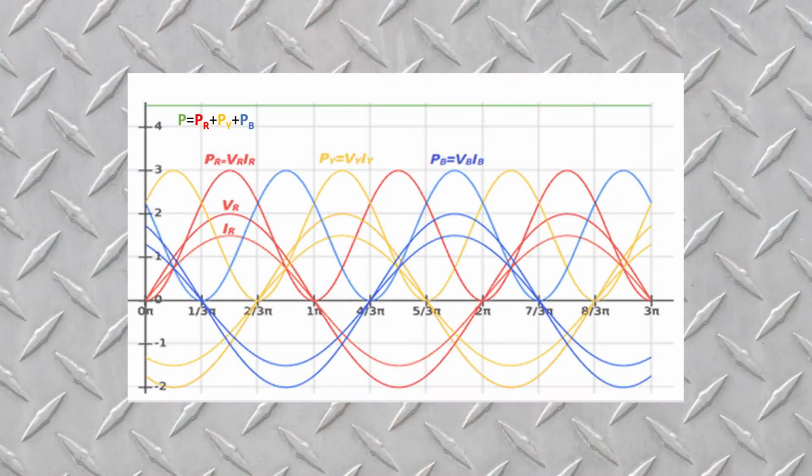Three-phase motors are a little more complicated, and often it's the bigger motors in industry that use the three-phase power, where the same 60 cycle, which can be any voltage, is going to have three different lines coming in, and each of them will be 120 degrees out of phase with the others. Now, as you can see, we have a red line, yellow line, and blue line, all representing voltage, and all of which are 120 degrees out of phase from each other.